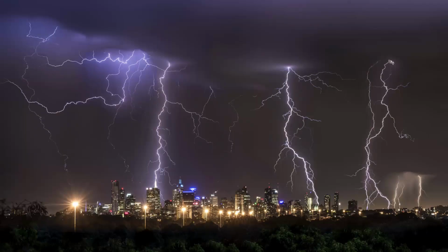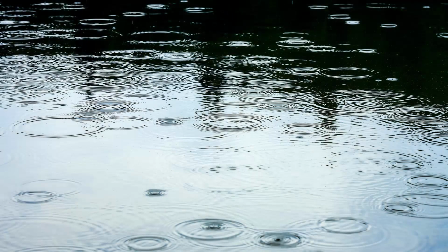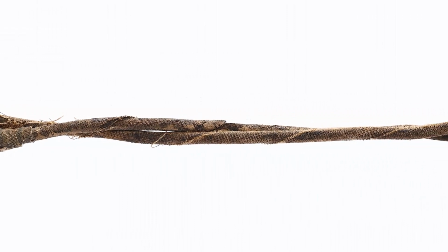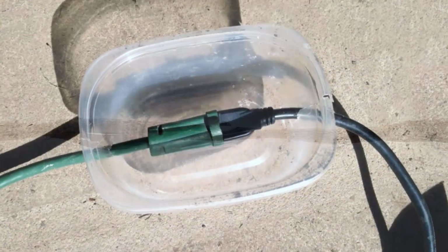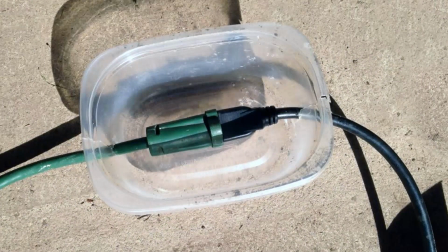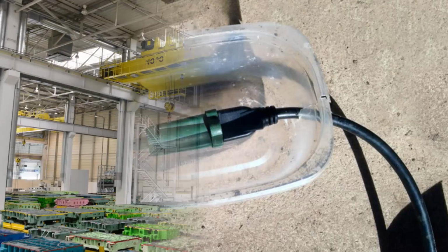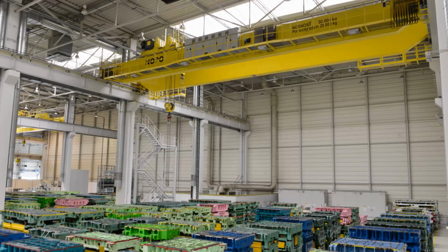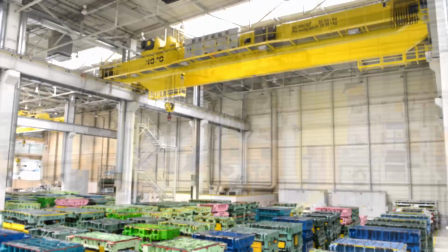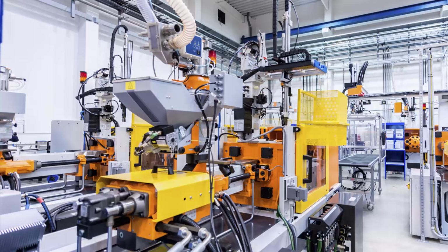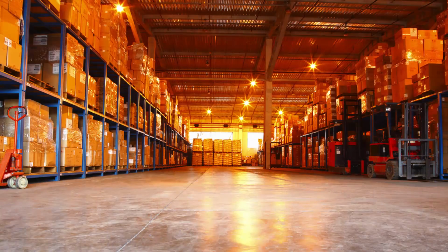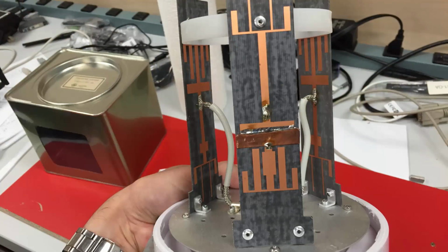Another possible issue for outdoor applications is moisture getting inside the cables. This can happen if the weatherproofing has been compromised by age or if it was never actually used in the first place. For indoor applications with lots of metallic surfaces or objects that are reflective for radio waves, such as a factory floor or a warehouse, we recommend using MIMO antennas rather than more conventional types.